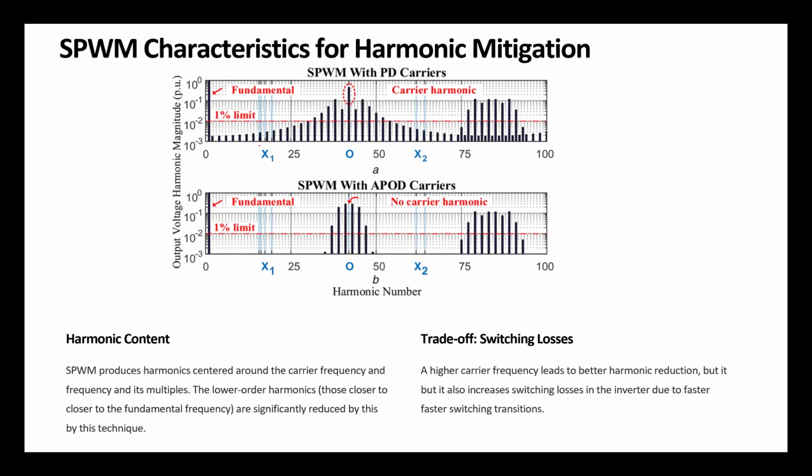But there is a trade-off. If I increase my switching frequency, we already talked about that when we introduced the MOSFET and IGBT in the first week. What would be the consequence of that increase in the frequency? Power loss, because the switches have loss when they go on and off. Because of that power loss, we said that there is a very high temperature rise in switching devices.